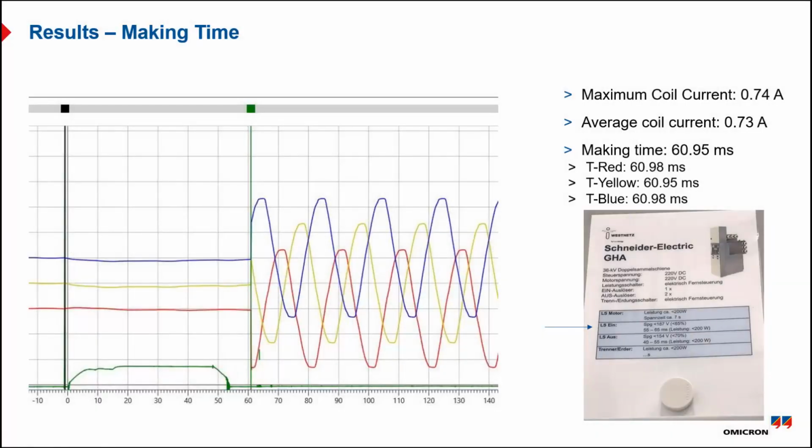Then we see a closing time. Similarly, there was no voltage, and suddenly when the breaker closes, then a voltage signal appears. And again, we can do 3-phase timing measurements and compare it with the corresponding opening time measurement from the manufacturer. So this is quite easy as you see, and once these indicate any problem, then you can do further measurements to confirm what the problem is.